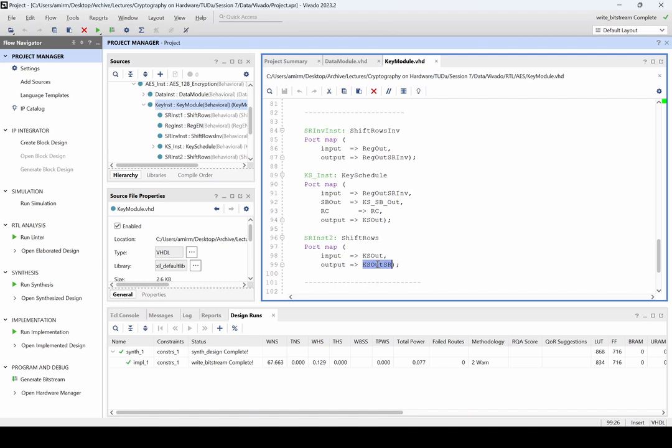It's not necessarily the best and most optimum way to implement the AES using 4 instances of the Sbox and 1 instance of mixed column. You may come up with another solution, saying that, okay, this doesn't need to have that many shift rows and shift rows inverses. Although they are free, they complicate the implementation or understanding of the implementation. But you may pay some extra clock cycles for that if you implement it differently, or you may implement it in a better way with a better trade-off with respect to area and latency.